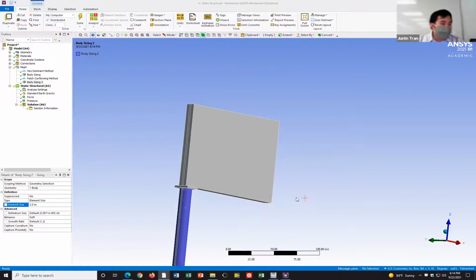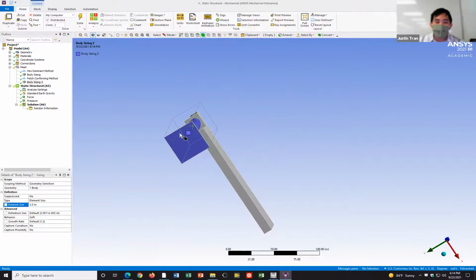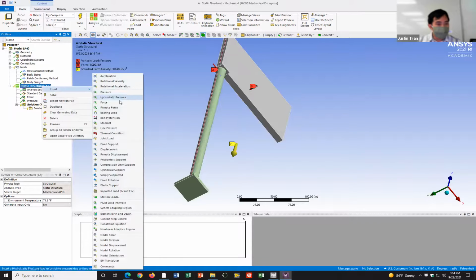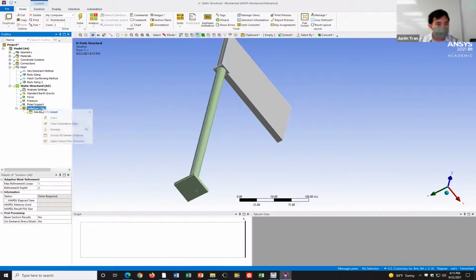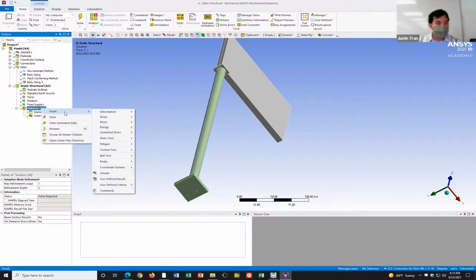Oh, yes, fixed constraint. Don't forget your fixed constraint, everyone. Your signpost is going to be fixed to the ground, so it's going to be on the bottom surface. I think I just mentioned it in a sentence at the end. That would help. Should we highlight just the bottom, or the whole thing? Just the bottom is fine.